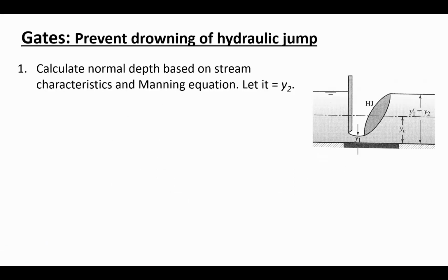Now, on Monday, we talked about hydraulic jumps. And I told you that how much you open the gate controls the location of the hydraulic jump. And remember, the ideal situation is that the tailwater rating curve and the jump rating curve are on top of each other. And all that means is that the flow depth that's naturally going to occur in the channel downstream, so in other words, Manning's equation, solve for depth, that depth is the conjugate depth of the flow after contraction